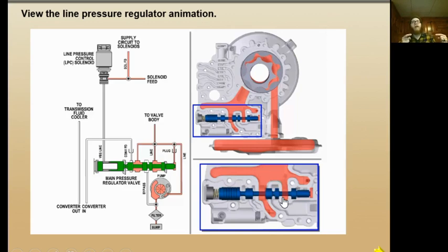Well, now I'm in second gear and I'm about to go up a hill and I need the engine to really work. Well, I step into the accelerator more, into the throttle more, which opens up my throttle valve more. It's either attached right directly by a cable, or in some cases it was vacuum actuated. We know how vacuum changes as we open our throttle. Less vacuum with a wide open throttle, maximum vacuum with a closed throttle. So going up a hill, I step on the accelerator pedal. That opens up that side, and now all of a sudden the pressure can increase and push back against the governor's pressure, downshifting the vehicle, allowing us to get that extra torque multiplication, and up the hill we go.